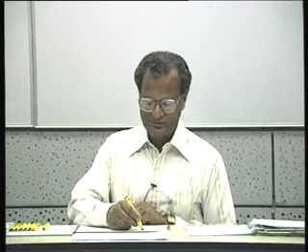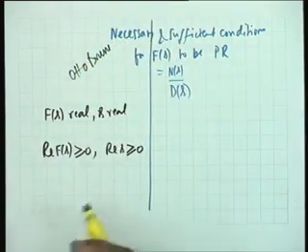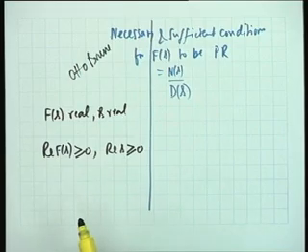So, what has been found out is people have worked on it throughout many years, and it was in 1939 a gentleman of German origin by the name Otto Brune, B-R-U-N-E. He wrote a PhD thesis at MIT, Massachusetts Institute of Technology, which for the first time gave the testing procedure for positive real functions, a simpler one than investigating the total s plane.